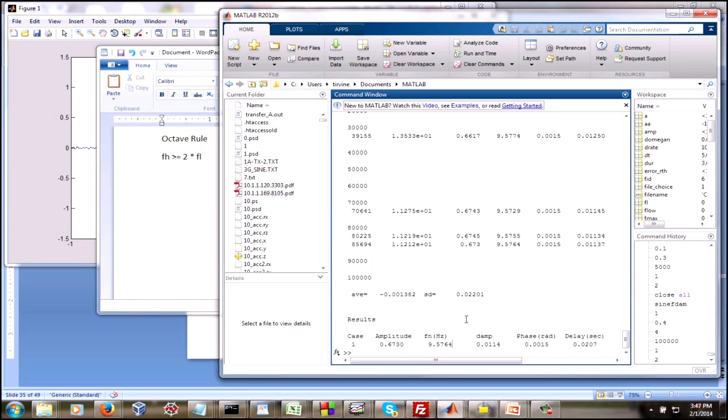It could also lead to excessive relative displacement of the payload within the Pegasus fairing, and we do not want the delicate solar panels of the satellite impacting into the inner walls of the Pegasus fairing. Otherwise, cracks or other failures might occur.